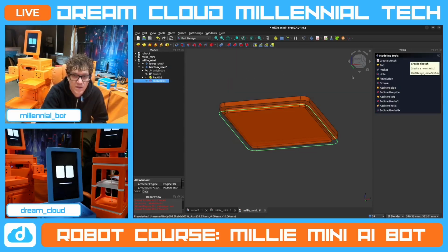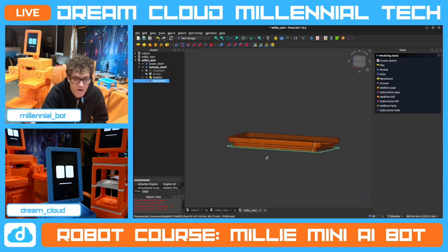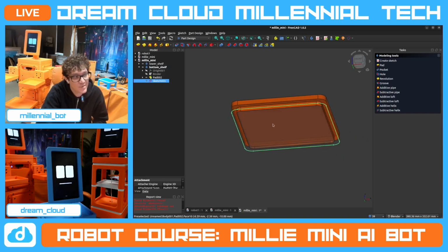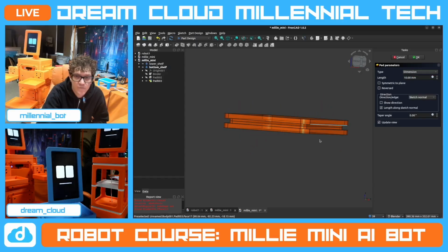We hit close. Now what we have is this floating drawing that's on the face, right? Like it's on the face plane, even if it's not touching the face. And then all we're going to do is hit pad, and it automatically defaults to 10, and that's what we want, right? So if we didn't want that, we could do symmetrical to plane, which would erase that 5, or if we did reversed, it would cover it completely. So that's not what we want. We want 10, we want dimensional, everything's good.